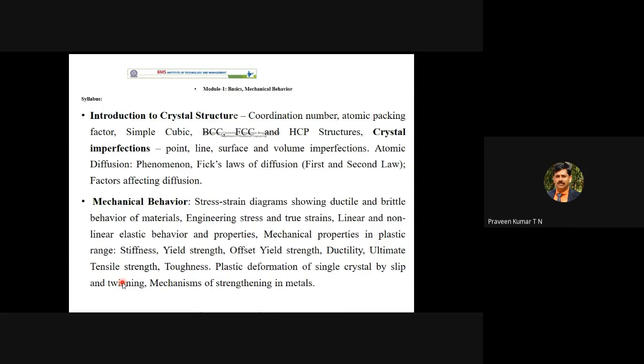Any doubt? Imagine we have a group of atoms. The atoms are moving randomly in the molten or liquid state at higher temperature. During the crystallization process, the crystal forms. We can use the term crystallization only for metals, in most cases. But not all materials crystallize. A material may solidify from liquid state to solid state but not crystallize, so it may be an amorphous material. During crystallization, it forms unit cells.